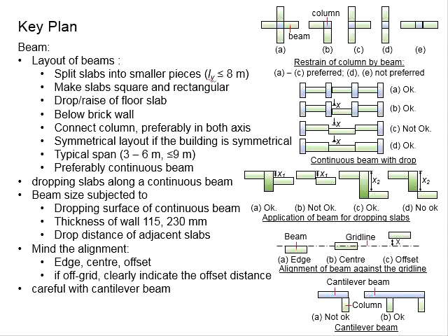And when you design the beam, the continuous beam is normally more preferred. If you can have the members to be continuous, that will be the best solution, as you will not have significant moment at the midspan, where your support can be used to withstand some part of the moment, so that the moment happening at the midspan will reduce.